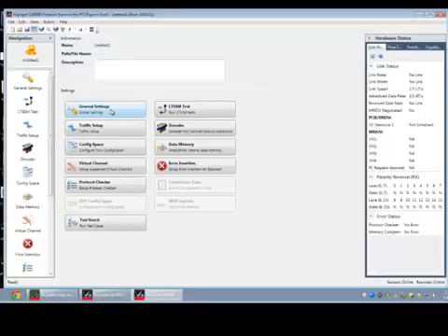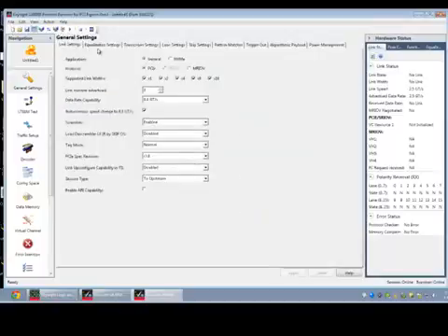So the first thing I want to do is go to General Settings, and in the General Settings, there are a number of different tabs for configuration. First off, I'm going to test a device. So I select my session type of connecting to the downstream. I'm going to operate as the root complex, and I apply that. And that configures my analyzer operation.